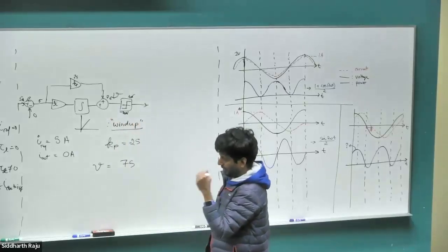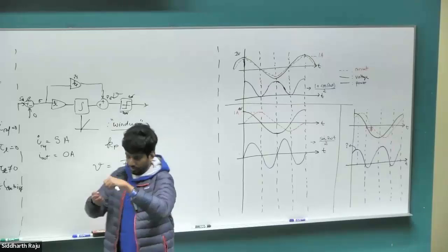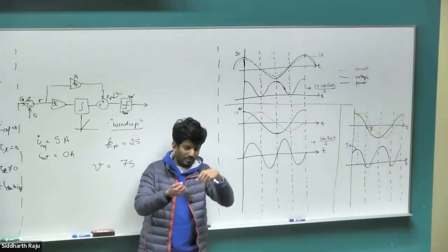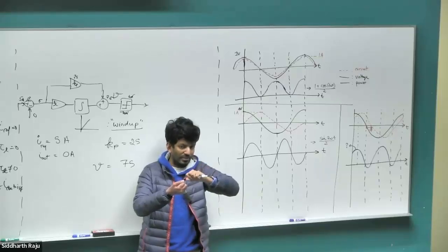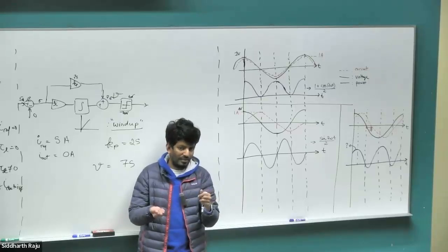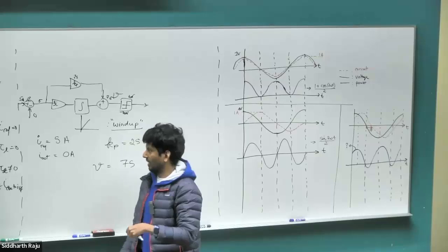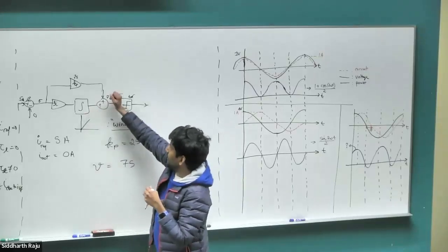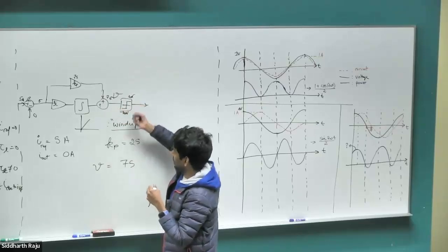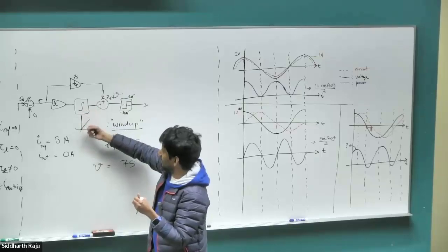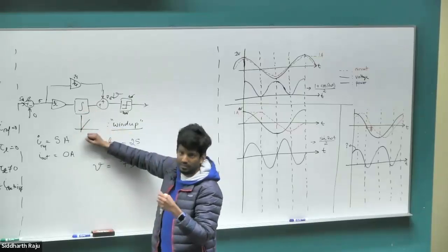Because it's like those toys that you would have played as a kid, right? Maybe I'm too old, I used to play with these toys as a kid. You have this screw kind of thing that you can wind up, and there are only 3 or 4 turns you can do, after which it's just useless. You can wind more and more, it doesn't add any value. There's a spring that just breaks contact after that. The same thing happens. After the output has reached the maximum value the converter can do, if this integrator keeps getting wound up more and more, it's not actually creating anything.